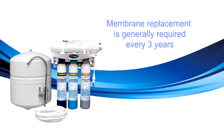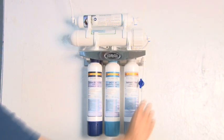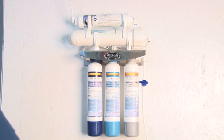Membrane replacement is generally required every 3 years. The frequency depends on the quality of the feed water. The system should be disinfected when the membrane is replaced. To disinfect the system, follow these steps. Number 1, turn the water off and drain the storage tank.